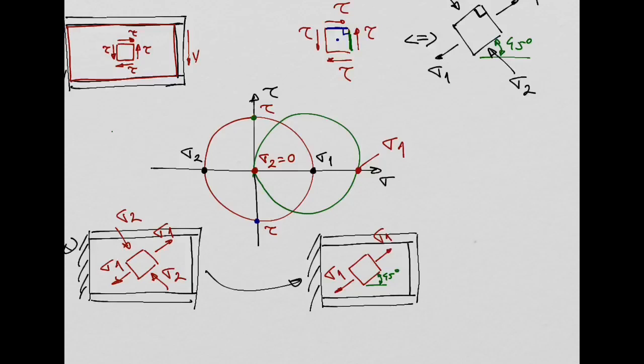So basically, it's translated, right? Okay. So, do you understand this more or less? What happened here? So basically, we are letting this web buckle in the direction 2, and what we are saying is that the web is going to carry all the load now. So 100% of the load is going to be carried along this 45 degrees direction and in tension.